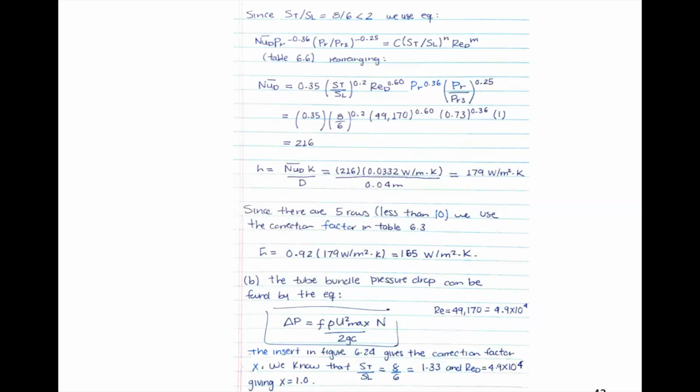If I want to know the heat transfer rate, then I just plug in that H value times the surface area, but not only for one tube, you need to consider all tubes, times the log mean temperature difference. But the problem in this case just asks for H.